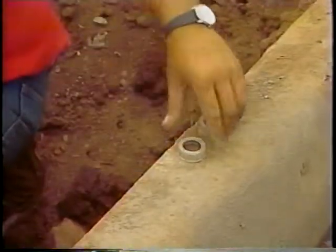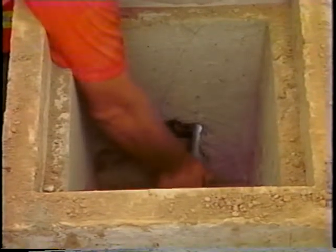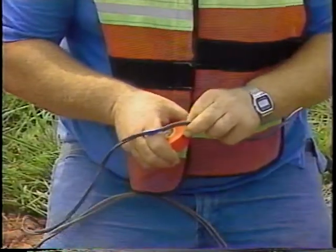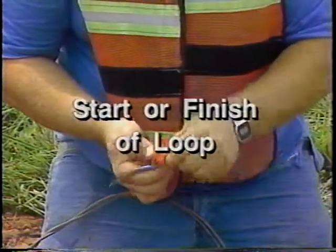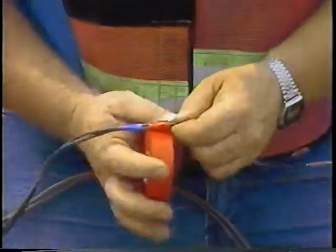To protect the wires, attach a non-metallic bushing and tape the wires for several inches on each side of the bushing. And remember, it is important to tag each wire identifying loop number and the start or finish of that loop. In our example, we are using colored tape for tagging.